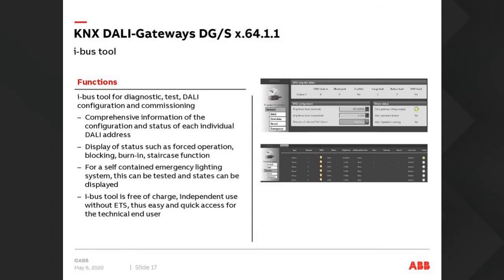Again, we have the different functions in the DALI tool. We can look at the lamps. We can see how they switch on and off. We can look at groups. We can look at our DALI lines. We can actually do burn-in. We can do burn-in for our fluorescent lamps.